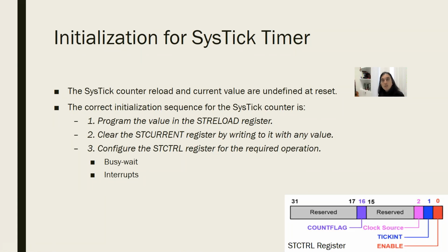The next week, we have changed the initialization routine in which we initialize both LEDs and switches. And the other week, when we learned interrupts, we have further changed the initialization for GPIO. We have made it possible to use LEDs and switches, and we also initialized interrupts for the switches. So the initialization routine depends on what you want to do with your system. So I will provide different initialization routines.